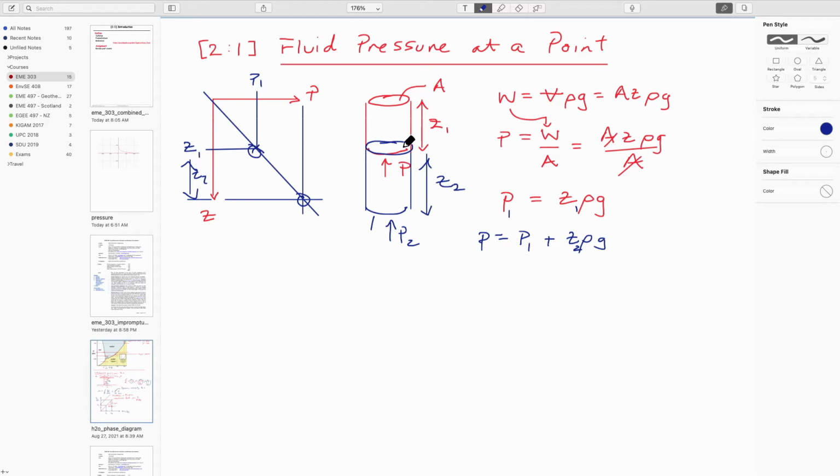And so the point is that as elevation goes down, we can define this as pressure equal to density times gravity times depth, if you like. Should call it H perhaps. H might be better, but let's not do that now. And we can also write this as unit weight times Z. And so that's the way that we can define this behavior.